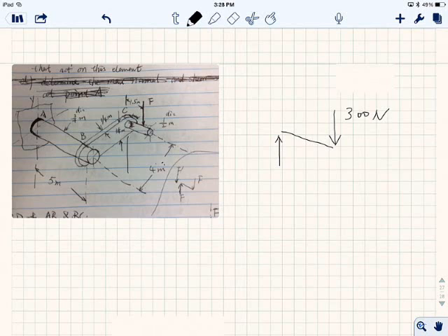For a cantilever beam, when you take away the support, you have 2 different resultant reactions. One is this force over here. Let's just say this is C. Let's just say this is F, all right, at point C. At the same time, it is going to have a moment. Let's say this is MC, right? To balance it, because for a cantilever beam it is like that.